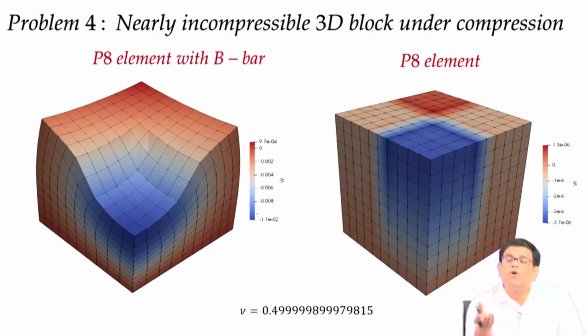There are two important variational formulations for this kind of finite element. One is Hellinger-Reissner, a two-field variational formulation. It can be based on displacement and pressure, displacement and stress, or displacement and strain, so three kinds of Hellinger-Reissner formulation are possible.